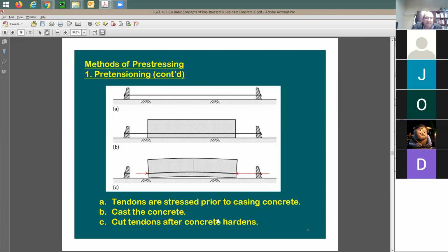Now, what do you expect? You're gonna have an axial load and moment. So this is gonna be equivalent to what? An axial force like in here, right? And a moment, and the moment is gonna be acting like this, with compression at the bottom. So the arrow is gonna be on this side, right? So what do you expect? The beam would like now to camber. It wants to go up. You see, it is lifting up.